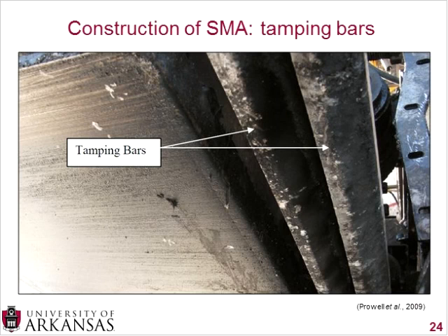And this is just a picture of the tamping bars. This is the underneath portion of a paver. The material is coming from your left, and it'll be laid down, and those tamping bars will apply an initial compaction right after it comes out of the paver.